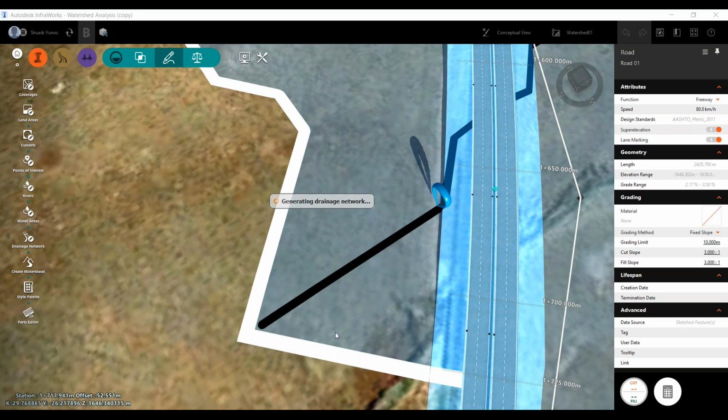So again, this will only work if you have an assembly that has a curb and channel or a curbing where it will make sense. If you just have a road there with 2 lanes, it's not going to work because the software does not pick up the channel. So it's also foolproof design, if I can put it that way. Okay, and it makes us check our work, and it also shows that the software has intelligent features. And this is a lot of intelligent features, especially for a conceptual design tool.